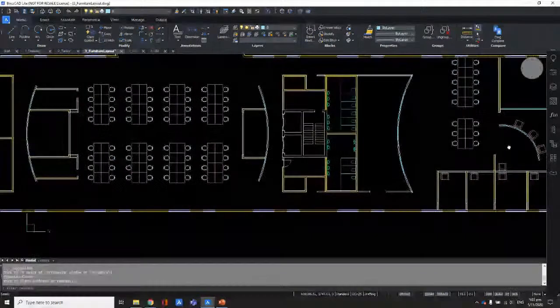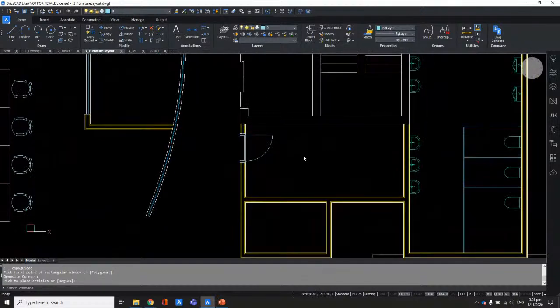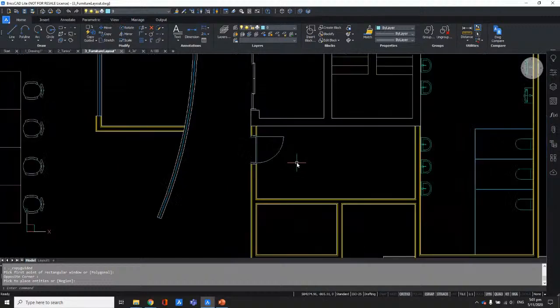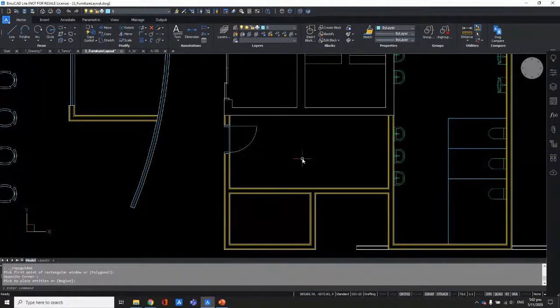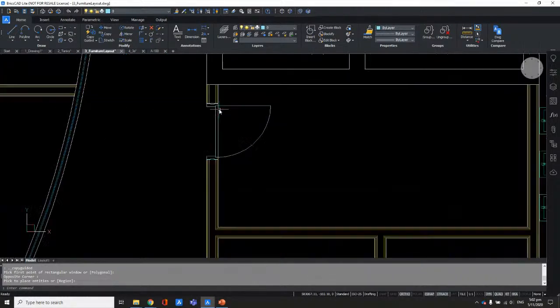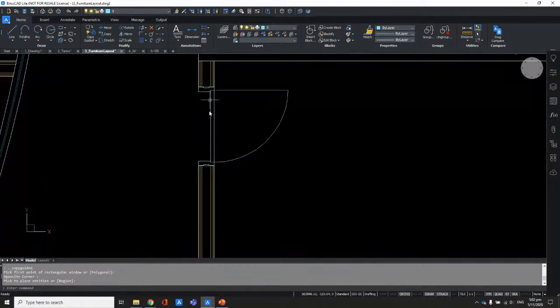So let's move here to, okay, we have a door here. This door may be something that you want to reposition, let's say along the process of the design or the construction. It always happens that you need to change something. So this door now as a block reference, normally you would have to move this and then repair your walls, right?